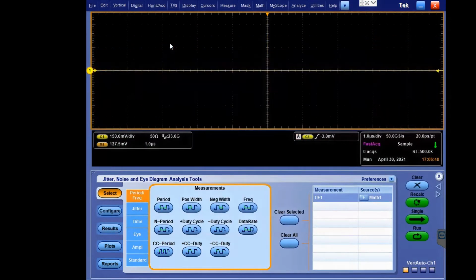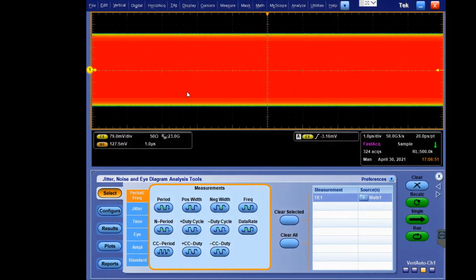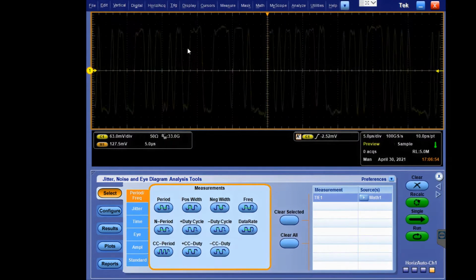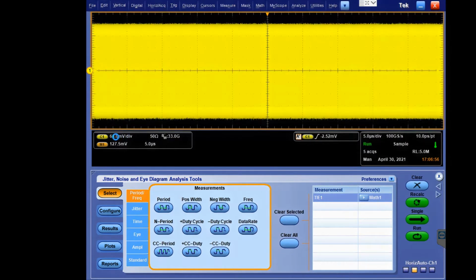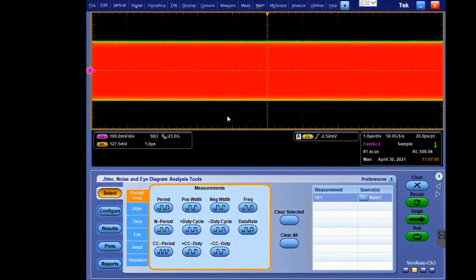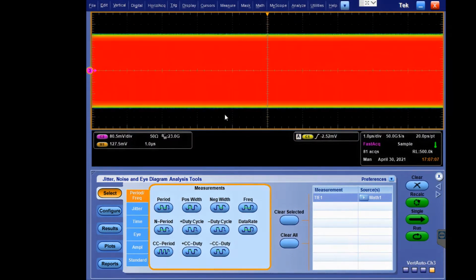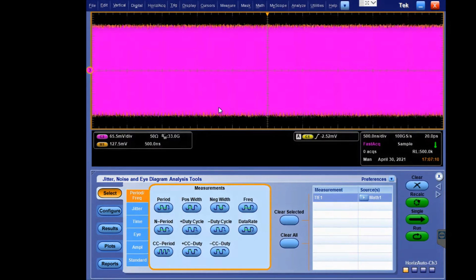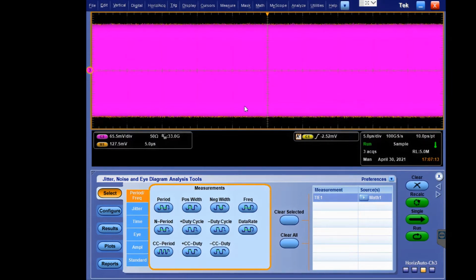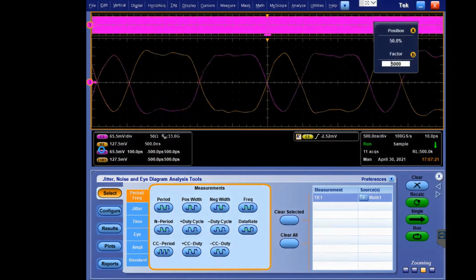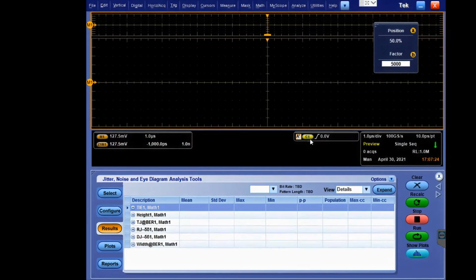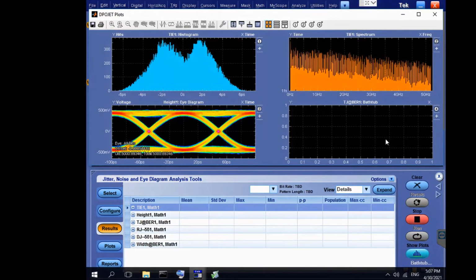That will basically do all the hard work for you, assessing the amplitude in fast-track mode of channel 1 and channel 3, and setting up the vertical sensitivity of the oscilloscope. So you will be using 90% of the grid to capture the signal, and thus you will get the best signal-to-noise ratio to quantify the signal for further analysis. Once the vertical scaling is complete on channel 1 and channel 3, they will be turned off, and there will be only the math one remaining, and the oscilloscope will acquire a deep memory of that differential signal.